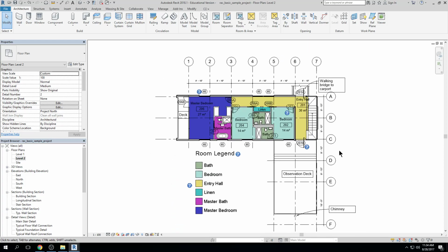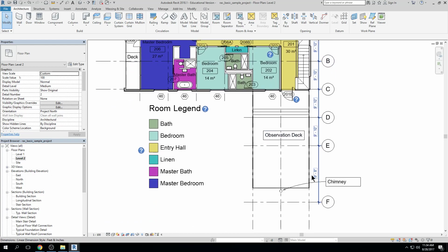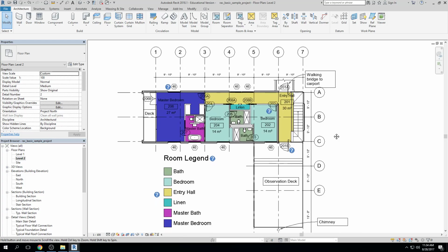Now, just like AutoCAD, when I draw things here, I draw them in real world scale. That means that if I draw a building that's 100 feet by 100 feet, I draw that building 100 feet by 100 feet. I don't, in my mind, scale it down so that it will fit on a piece of paper, like a 1/4 inch is equal to a foot. I don't do that. I always draw things the exact size that they are in real life. So that generally makes it easy. So this building right here, we've got about 10, 20, 30, 40, 50, 60 feet. This building is about 60 by 60, we'll say. And it's drawn that way.